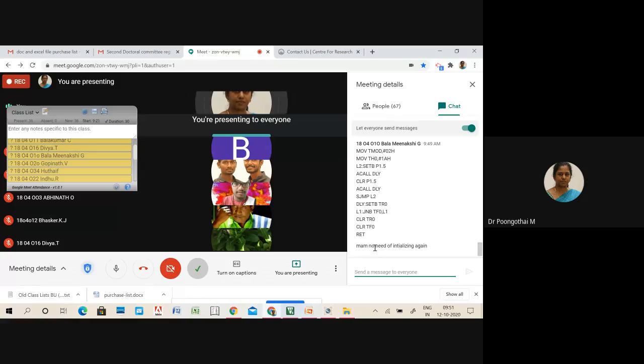How do you calculate the initial value of timer for different time periods? So the on time is 3 millisecond, off time is 10 millisecond. What is the logic for this particular application? Please tell me. So here you have to generate square wave with on time of 3 millisecond and off time of 10 millisecond on all the pins of port 0. Here you have to use timer 0 in 16-bit timer mode. Can anyone explain the logic of this program?